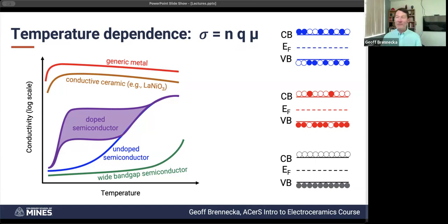So how much is too much for the dopant? It's essentially linear. If you put in a dopant, well, it depends on the kind of dopant and the way it's compensated. So we'll get into defect chemistry later on. Let's say everything is ideal and perfect within a semiconductor. For every phosphorus that I put into silicon, I'm going to get one electron.